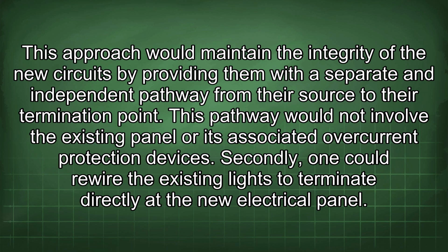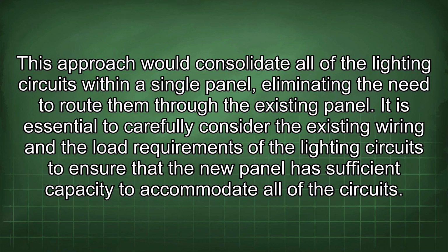Secondly, one could rewire the existing lights to terminate directly at the new electrical panel. This approach would consolidate all of the lighting circuits within a single panel, eliminating the need to route them through the existing panel. It is essential to carefully consider the existing wiring and the load requirements of the lighting circuits to ensure that the new panel has sufficient capacity to accommodate all of the circuits.